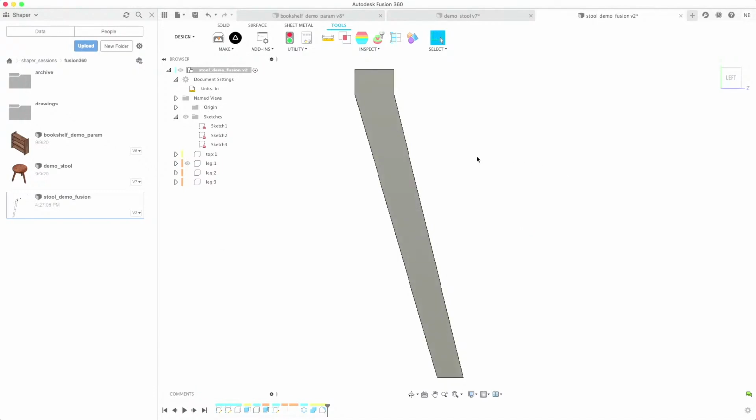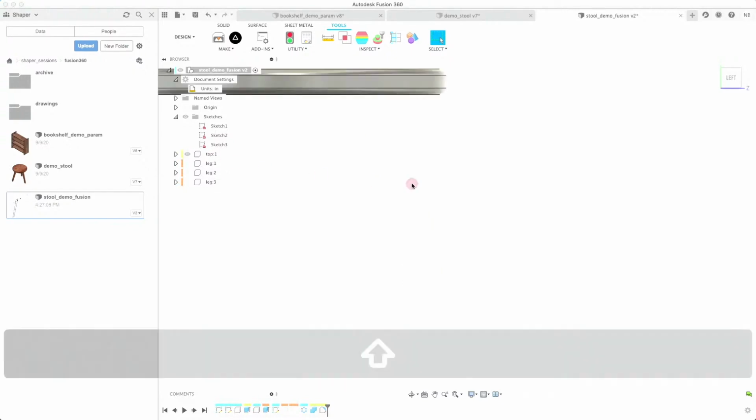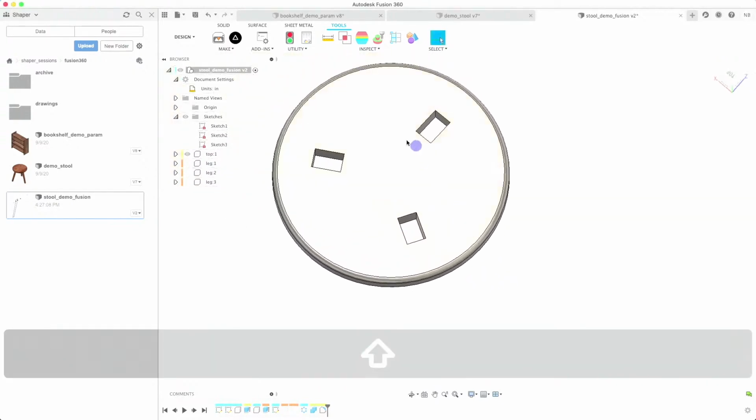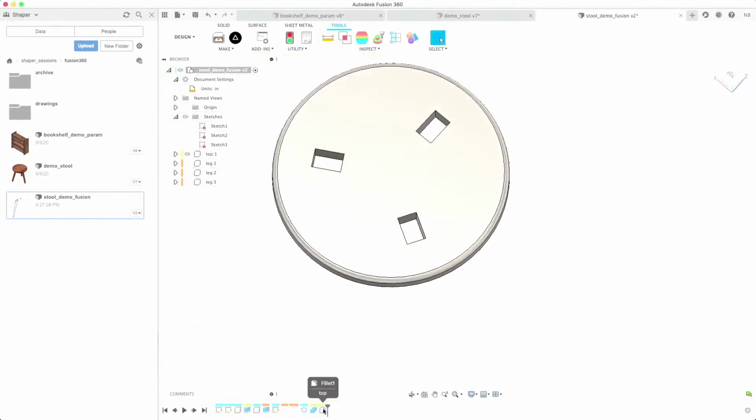We're going to move on to the next thing that we need, which is going to be the top profile. So we'll hide the leg for a second, open up this top, and again, we don't want the fillets. We just want that raw profile again. Oh, and actually here, this is a little bit of a fun one. Because I suppressed the extrude feature to get that nice profile on my leg, these are now square. You see that we don't have the right thing going on there.